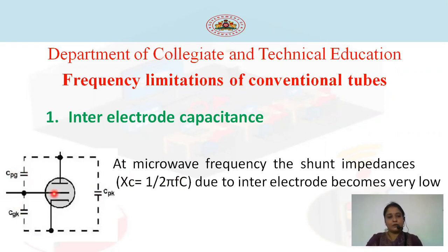Physically we have not connected these capacitors, but that particular region will act as a capacitor. The region in between the connected P and N, that depletion region, is acting as a capacitor. At the lower frequency ranges, these won't come into picture. Why? Because if f is low, Xc is very high, which means it will be like an open circuit. Therefore, it won't come into picture. It is like not connected.